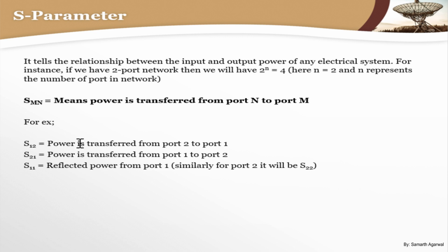The other thing is that S11 is the reflection coefficient, as we have studied, and S12 or S21 represents the transmission coefficient, because the definition is the transferring of the power and the reflecting of the power. That's why they are termed the transmission coefficient and the reflection coefficient.